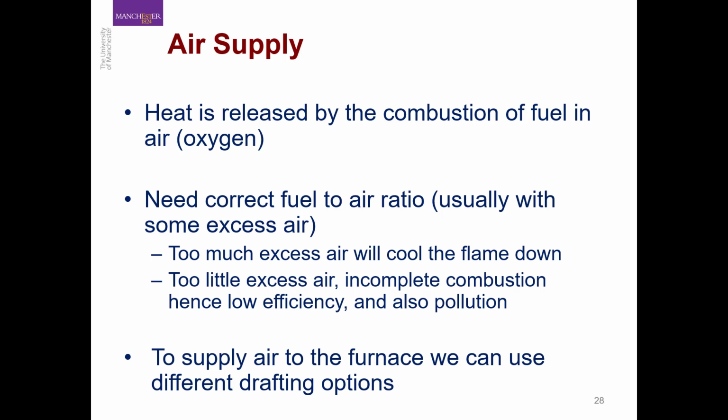You will also increase the volume of the flue gas and the heat loss, because you are giving too much excess air, and as such the whole volume of the system will increase, and that is going to further decrease the efficiency of the furnace.